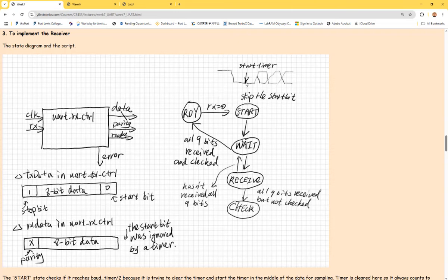Okay? And clear it for the first bit. So for the first bit, only count to the half and clear it. And after that state, you count to the full count max for the following states. So the first bit, you count to the middle, you clear it. And in the future, you count to the full count max, which will give you the bit width count.